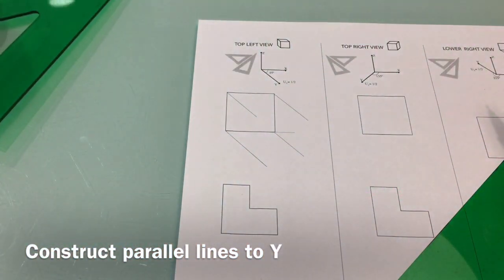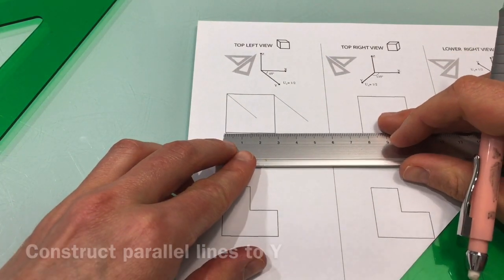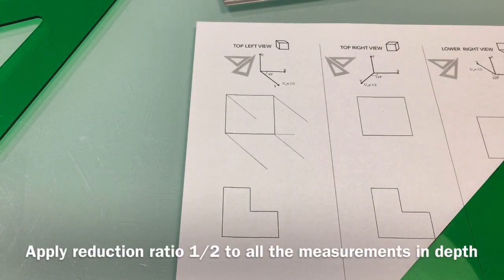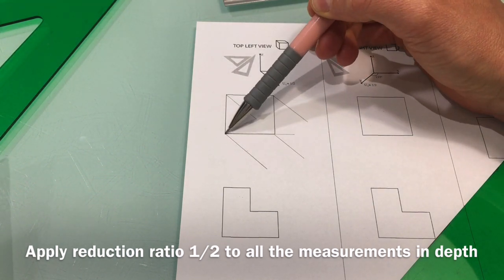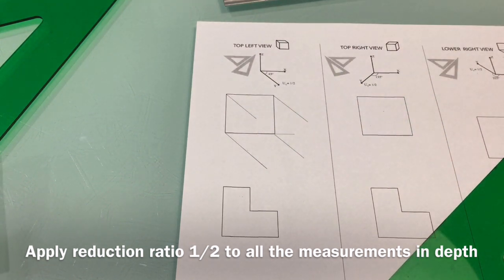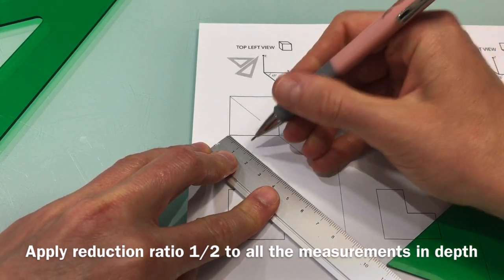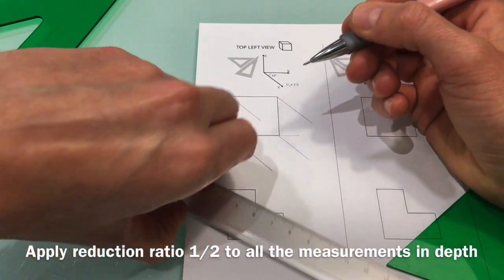A cube has the same length of edges, and if you take your ruler, you will realize that the rear face is 3 by 3 centimeters. When drawing in the cabinet projection, the depth of the object is foreshortened. That is, we reduce to the half the 3 by 3 to show a more realistic view of the object. The half of 3 is 1.5. This is why I'm going to take my ruler and I will measure, instead of 3, just 1.5.